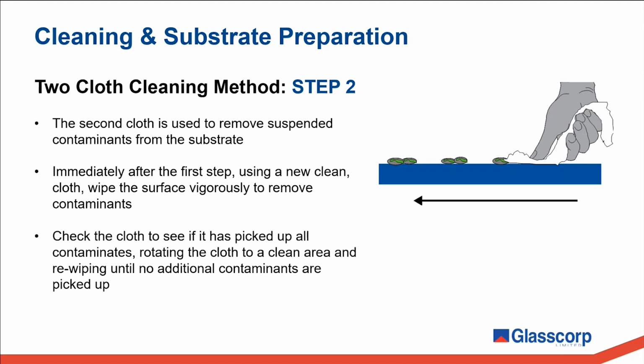A few important points to make here. Solvents must be removed with a dry cloth before the solvent evaporates, or the cleaning won't be as effective. And some surfaces or weather conditions will allow a small amount of residual solvent to remain. And in this case, the surface must be allowed to dry first.